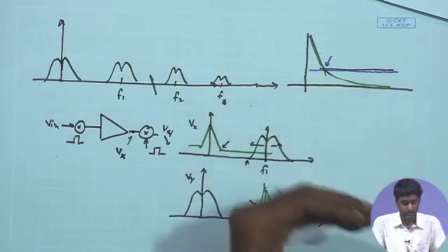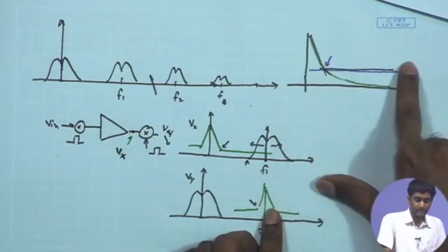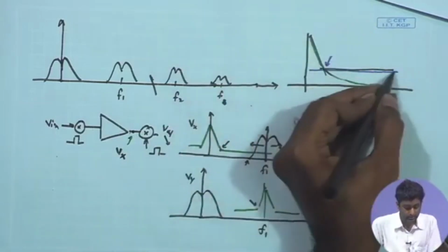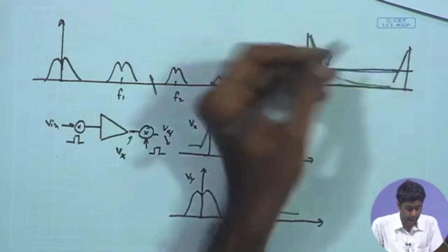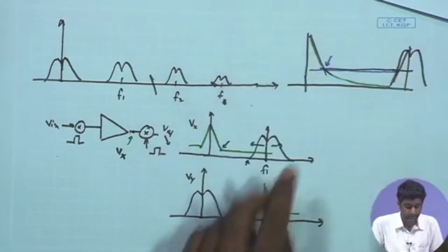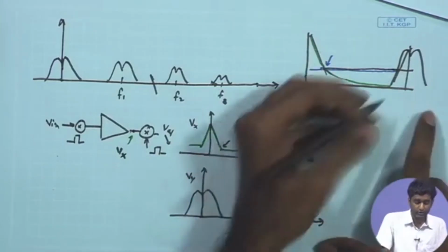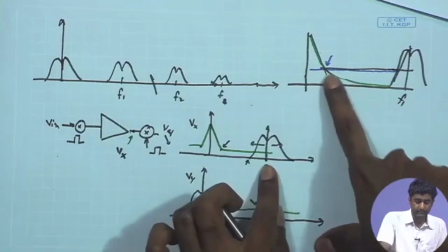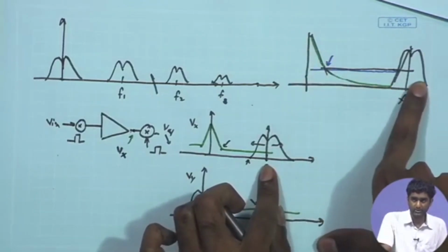So, we would like to take maximum possible advantage of the chopping and try to shift the signal frequency even higher by applying a much higher chopper frequency, so that my signal after chopping is sitting far away from this 1/f corner, and also by that chopping frequency f1, the tail effect of this 1/f noise has also diminished significantly.